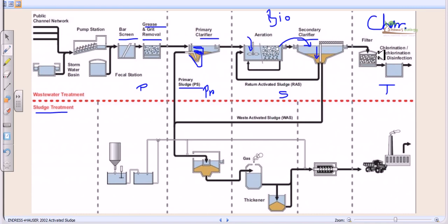So this is the flaw of this wastewater treatment. Or sometimes this chlorine can cause damage to us, because chlorine is a halide, and any halide is dangerous for the human body, or for any animal. If this chlorinated water, in a higher concentration, is directly discharged onto the streams, it can damage our freshwater flora. For example, fishes and phytoplankton, zooplankton, whatever is there, can be harmed by this chlorine. That's why we need to remove the chlorine to some extent, or bring the concentration of the chlorine down.